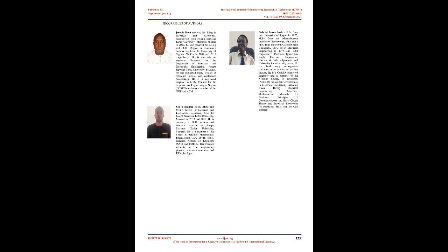However, the Budalal model estimated a higher percentage error for time availabilities of 99 to 99.999% with percentage error ranging from -76.3285% to -83.7181%. Table 4, Table 5, and Table 6 show that both the ITU-R and modified ITU-R models account for similar percentage errors for 99.99% availability for rain rates of 60 mm/h, 80 mm/h, and 100 mm/h respectively, while the modified ITU-R performed best for 99.999% availability when compared to the other two models as shown in Table 5.